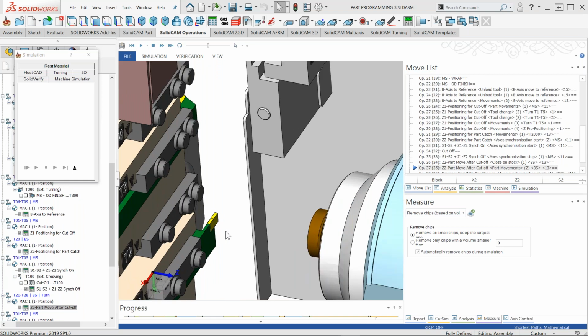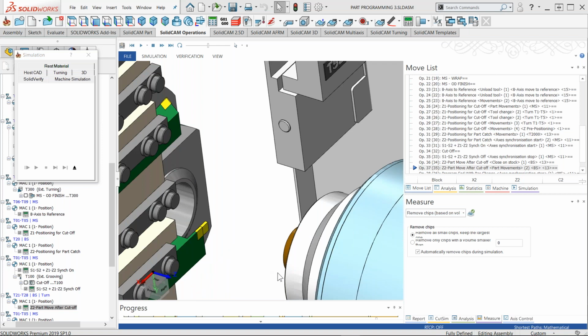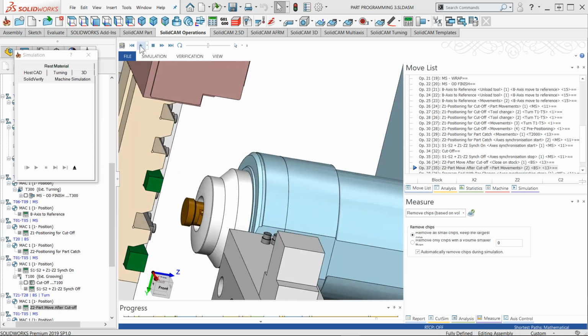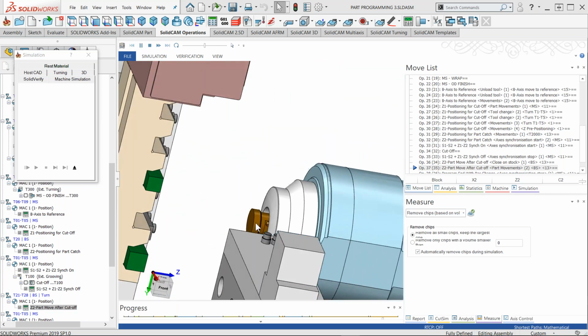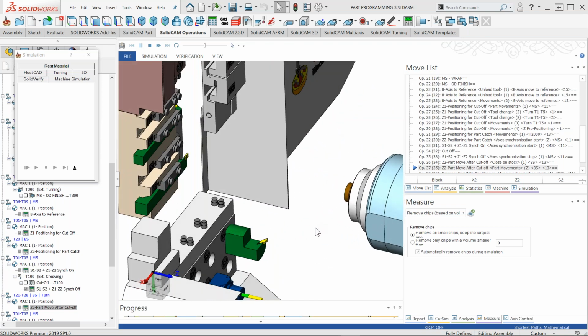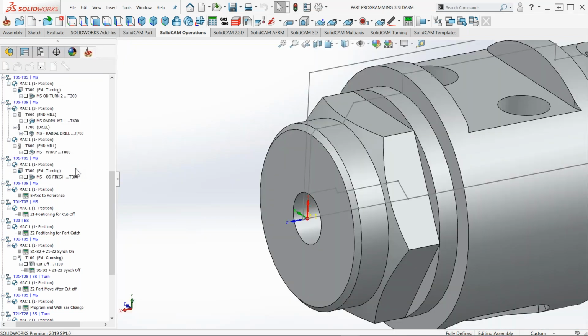Here we have the remaining bar. We could also leave the longer stock over here, so everything will be very nicely simulated. In this case, I didn't do it, but basically you can imagine here the bar left at this position. In the stock, it's in X negative. And the remaining stock, as you can see, travels with the back spindle itself. And with this, we completed the cycle of machining of one part. Okay, I'll just leave this, and once all two parts are verified, you can generate a G code.